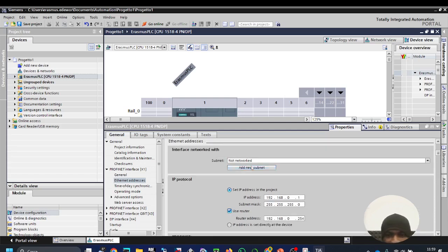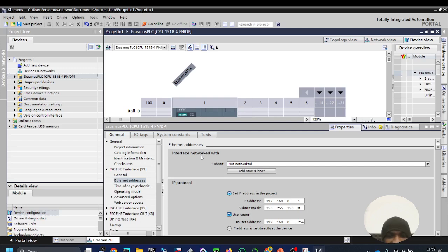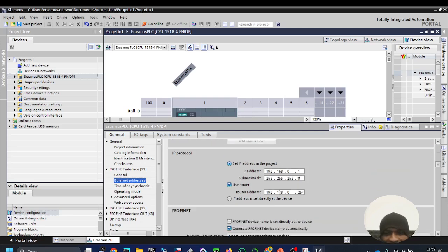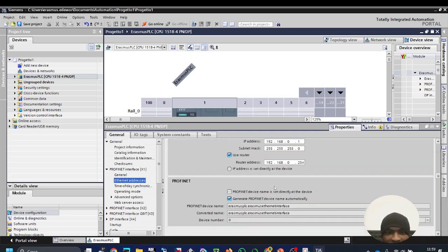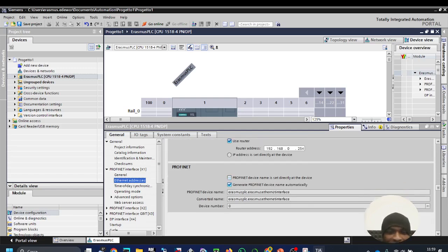Good. Now, if you come here, interface network width, you can choose this one, which is the first preference. Remember when we were trying to fix up this device, it says the first preference is the Ethernet IP, so you choose it, all right? So these are the basics of what you need to know about your first device hardware, which is the PLC.